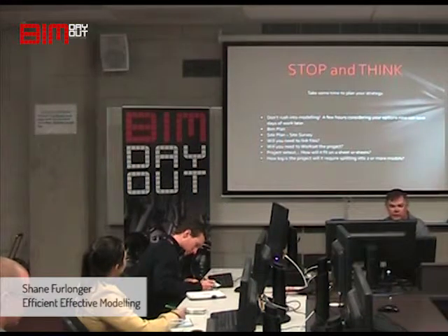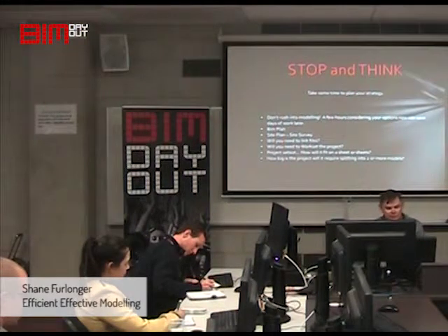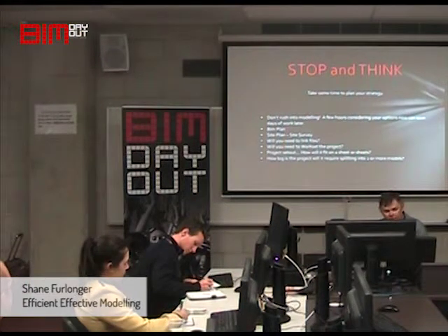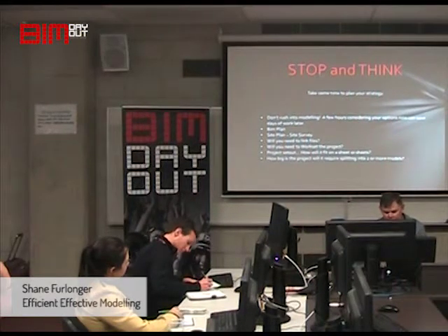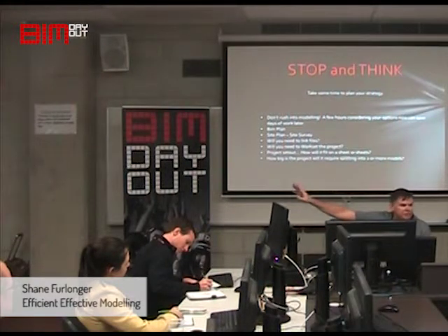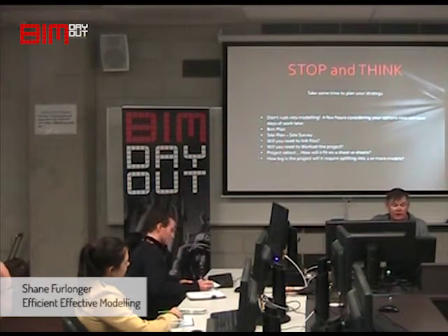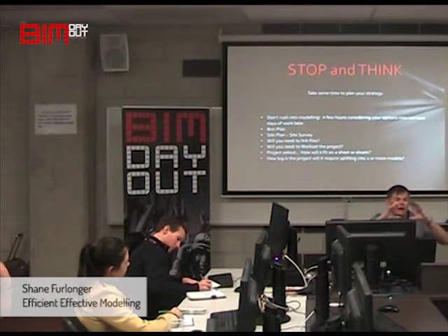Your site plan, 99.9% of site plans that are from Australia are useless when you first get them. The survey drawings are poorly done. They've got stuff on the wrong layers. They've got items that are out in space somewhere, and when you go to import them into Revit, you get problems, particularly if they're the stuff that's miles away. And it may be hidden. They might have turned the layer off when you're looking at the survey and you think everything's okay because you do zoom extents and it's all there right in front of you.